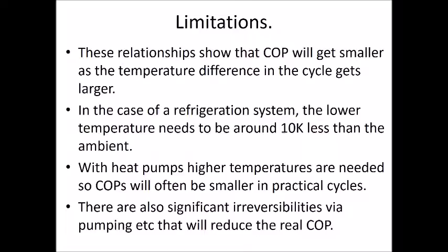I don't want it. So the bigger the driven temperature difference with a heat pump or with a fridge, the worse off the COP gets. So what does that mean? First of all, let's look at our fridge. So that means the bigger the temperature difference you run on the fridge, i.e. the colder you make your fridge or your freezer, the less efficient it is.